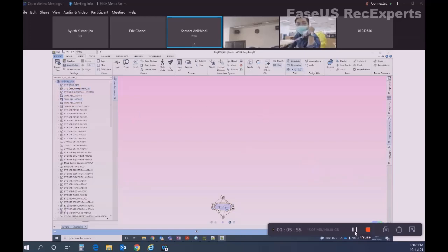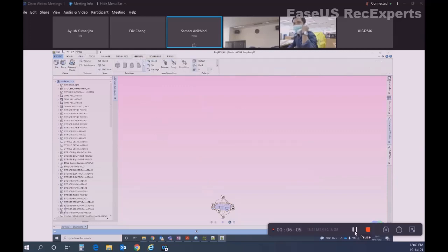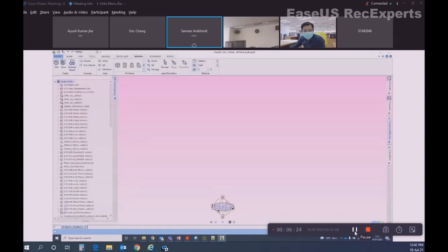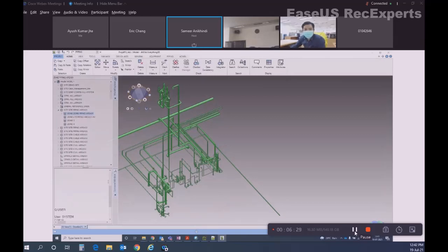Before that, I would like to let you know how to make your own site and zone, or you can start making your own hierarchy. In the general tab, be at the world level and create site. Okay, it's a read only DB. I hope in system user it will not give this. The reason this read only DB is coming is that you do not have write access to it. But let me go into system user quickly.